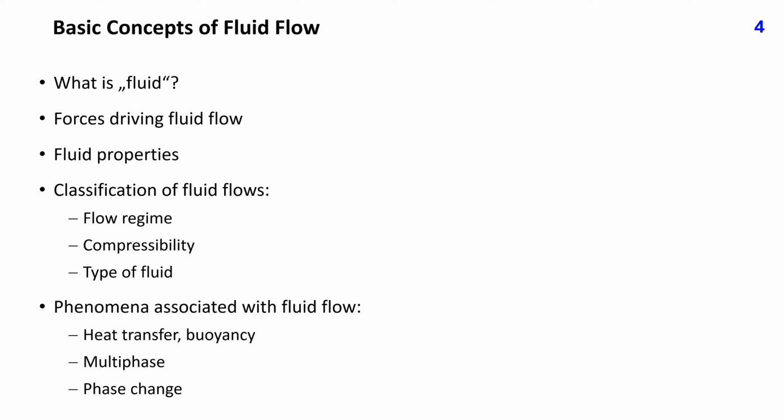Flows at very low speed are called creeping flows. This happens often in porous media and micro devices. As the flow speed is increased, fluid inertia becomes important, but as long as fluid particles follow smooth trajectories, the flow is called laminar. Laminar flows can be both steady and unsteady. A further increase in speed leads to instabilities which make the flow turbulent. The process of transition from laminar to turbulent state of the flow is an important topic on its own.